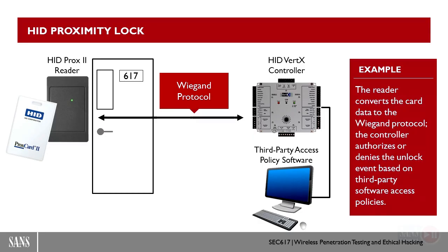These devices can speak Wiegand. They listen to Wiegand as it leaves the controller. Now we're capturing the Wiegand protocol on the wire. It can translate the Wiegand protocol on the wire and then stores it on the device. The two devices are interesting in that one is Bluetooth based, so I can connect to it with my phone over Bluetooth with an app on my phone, and I can interact with that.